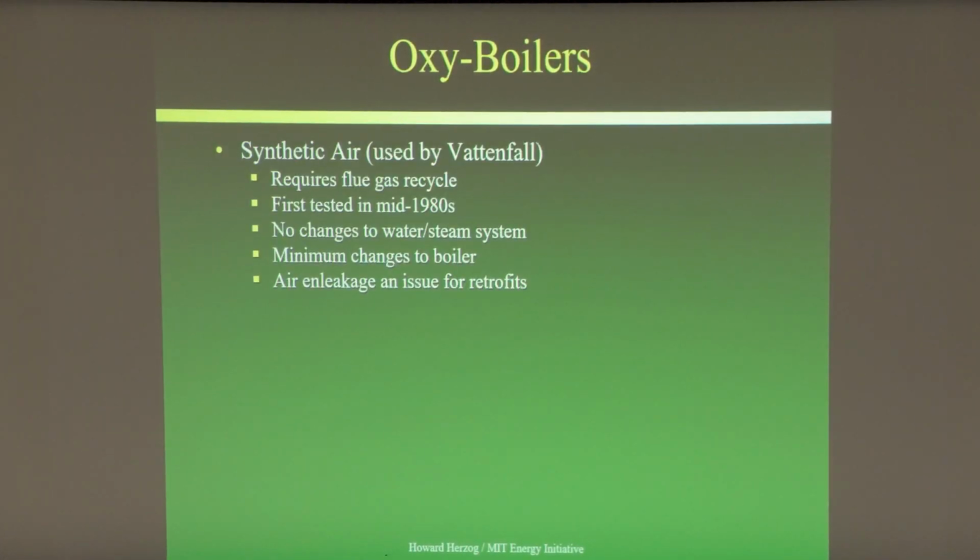Oxy-boilers, I talked about synthetic air, basically the recycle of the flue gas. This was tested in the mid-'80s, and you can use basically minimum changes to the boiler with the right recycle ratio. The big question, of course, is air in-leakage.